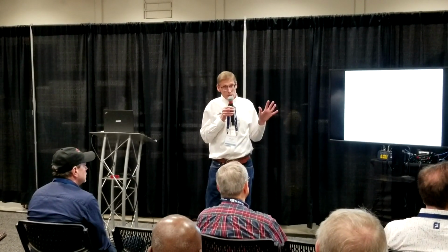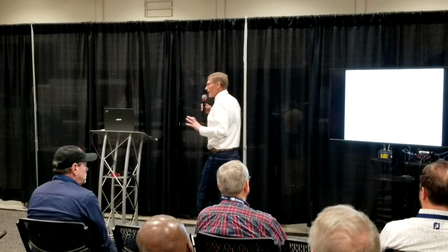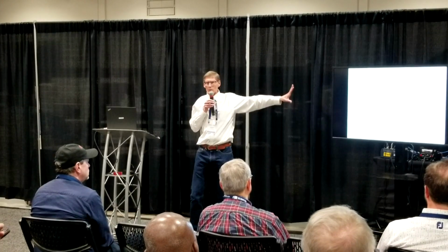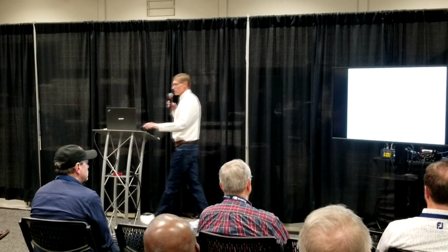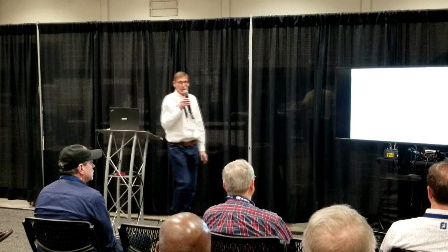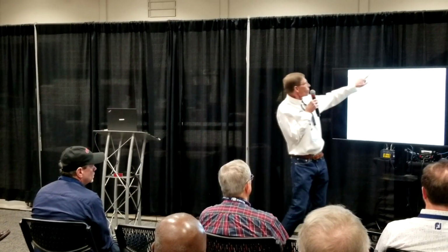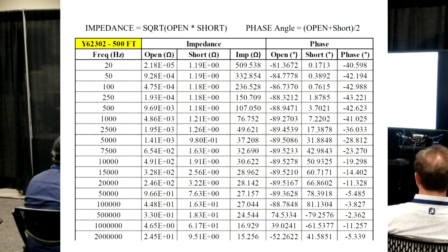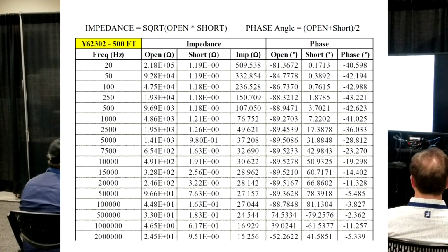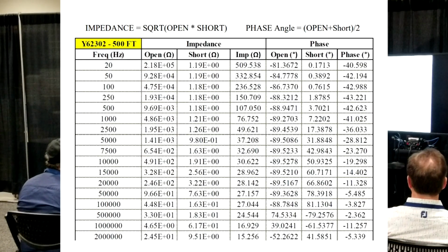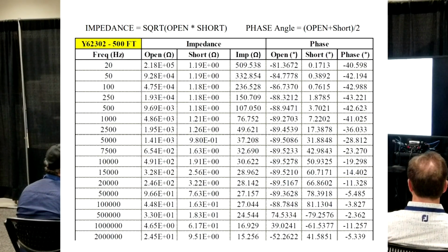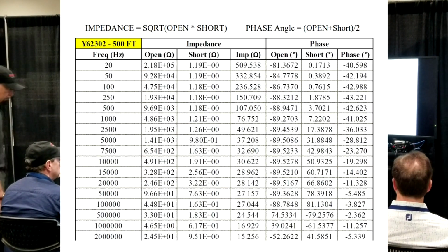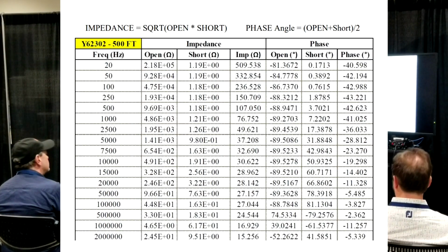And we'll start to see real cable measurements that support exactly what these theoretical graphs show. These were all done with mathematics, by the way. These weren't real cables, but I'm going to show you real cables measured. And here we go. This is the open short method, and everything's going to match up with everything we've talked about up to now. It's not going to, it'll all fall right in. The open measurement, okay, is when the cable is capacitive at the low frequencies. As you go up in frequency, the capacitive nature of the cable becomes less.